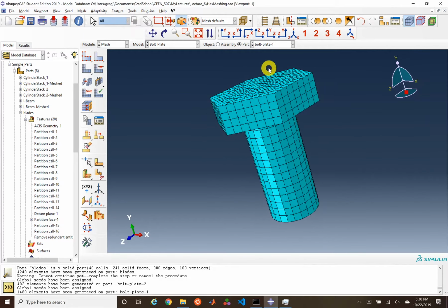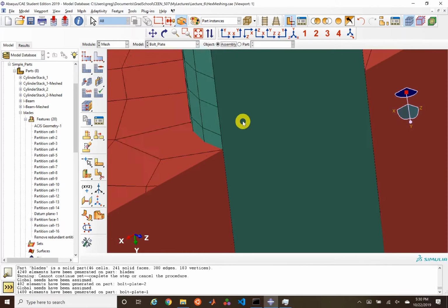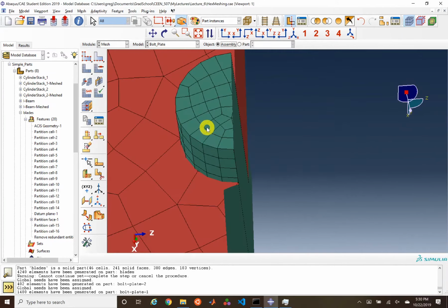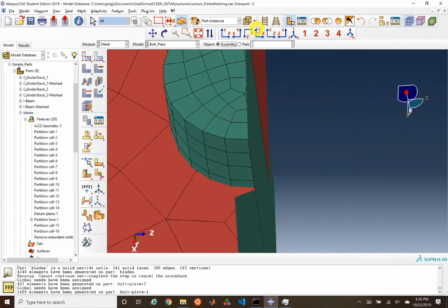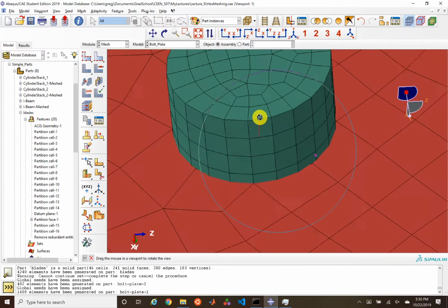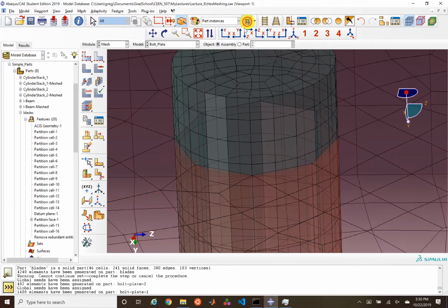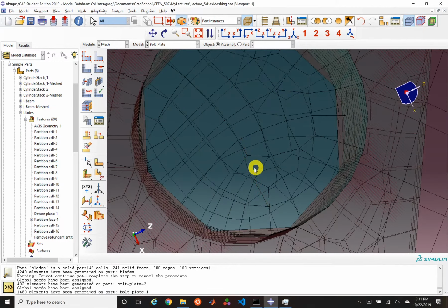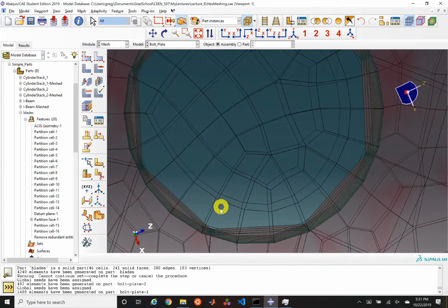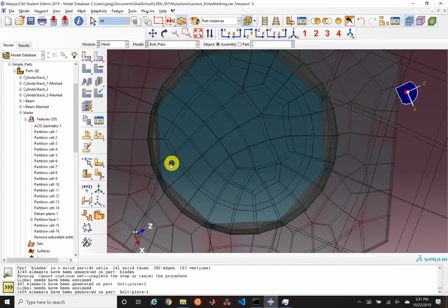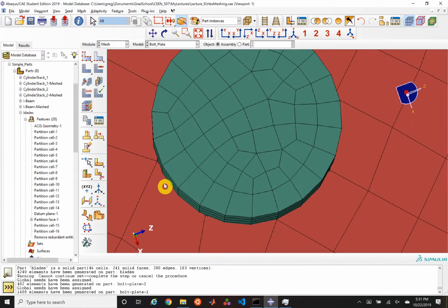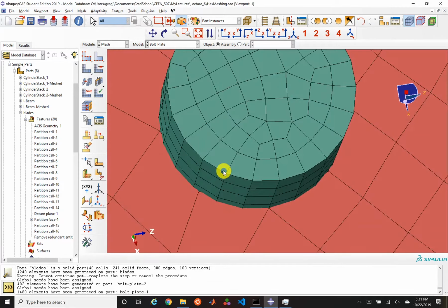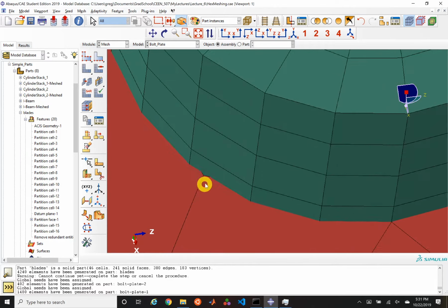So right now we're meshing the parts by themselves. You can't really see the other geometry. If we switch back over to assembly mode, let's turn off our view cut here. Now we've got this overlap that you might be able to see. If we look down the top, some of these hex elements of the coarse geometry have to be linear, and they're intersecting this green geometry.